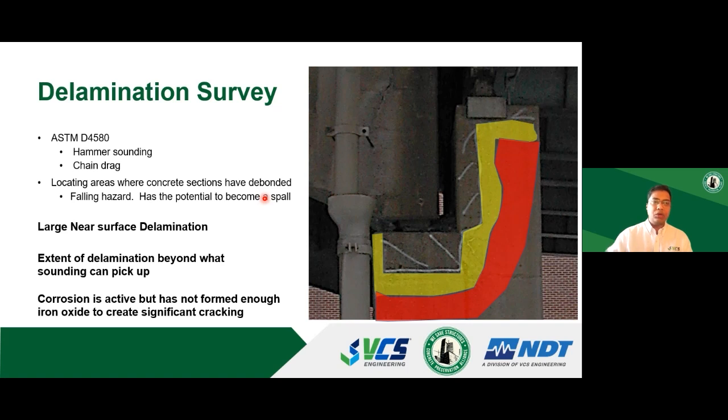You mark out those areas on the concrete deck, and then when it goes out to bid for the repairs, you see a sudden uptick in the repair quantities, and that's primarily because of a couple of things. One is hammer sounding or chain drag is not able to pick up issues of micro cracking. You might not be able to hear the micro cracking. It might not sound hollow, but it has a weakened area or less compressive strength.